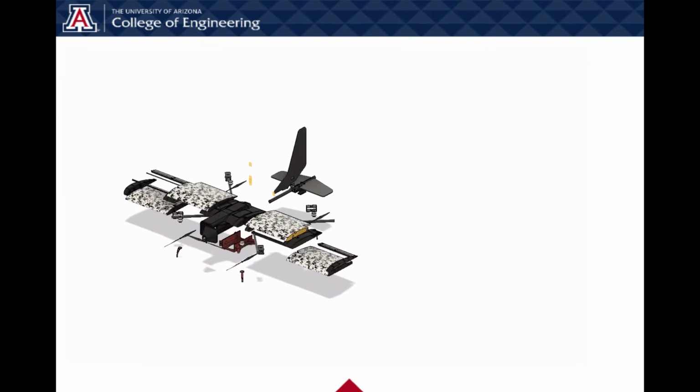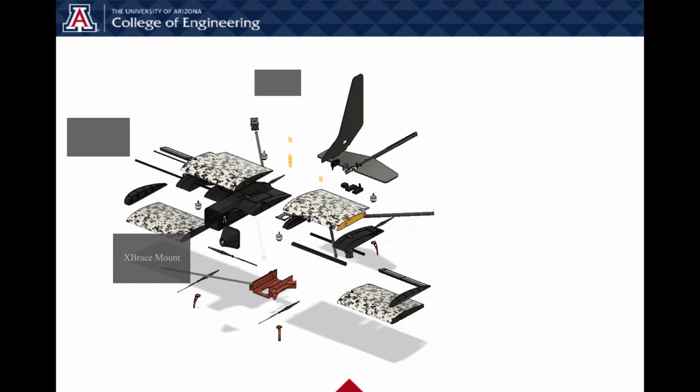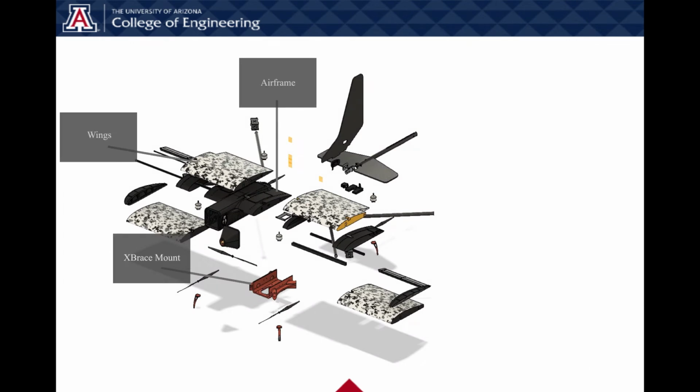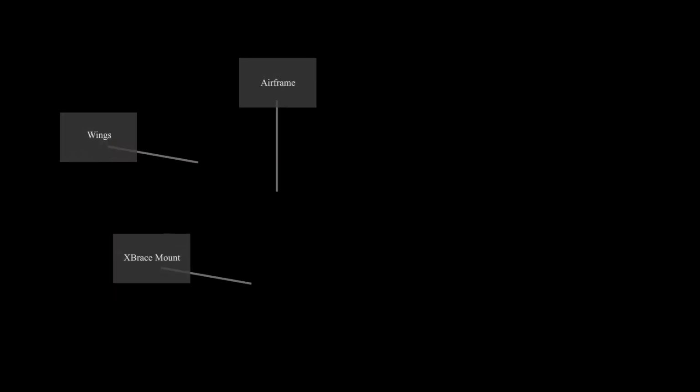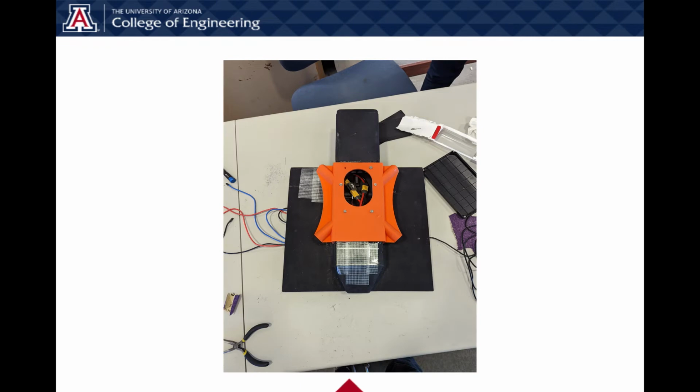The agreement we reached with Blackbar was that a plug-and-play option was preferred, where the system could be removed altogether to revert to the Storm configuration. The rethought design is what we call the X-brace. This is a 3D printed component that attaches directly to the underside of the fuselage, bolting directly to the existing payload bolt pattern. This rigidly controls the motion of the individual VTOL motor spars, as well as routing the motor cables directly into the fuselage to decrease parasitic drag.